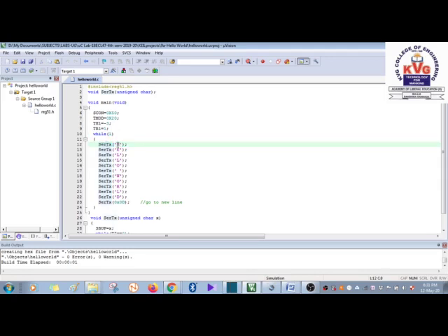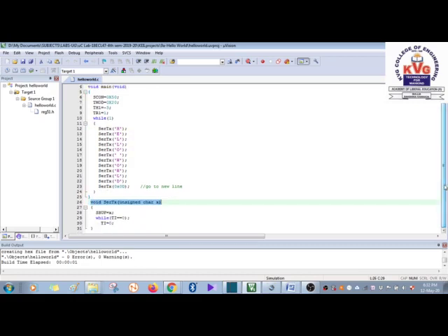You're going to send the character H. So when you call this function, it comes here, and that H is actually x. So H will now go and sit in SBUF. The timer takes care of the speed of the transmission. So H is now sitting in SBUF. After that transmission, TI will become 1. It has been set to 0. TI will become 1. So when it becomes 1, it means the transmission is over.